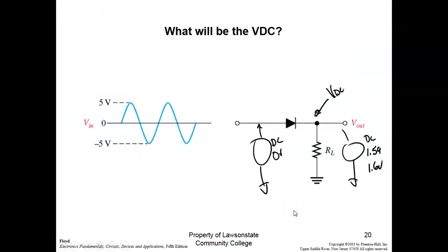So that makes sense, Brian? So everybody got 1.6 volts? So this is V peak over here. Here it'd be 5 volts, and over here it'd be 4.3, right? Because now we're on this side. And then we'll come up here and divide that by 3.14, and this should give me volts DC.